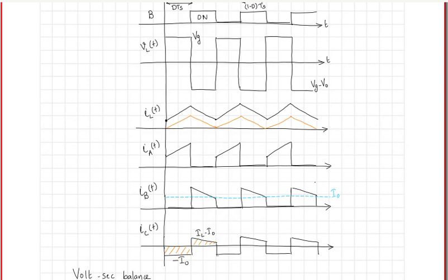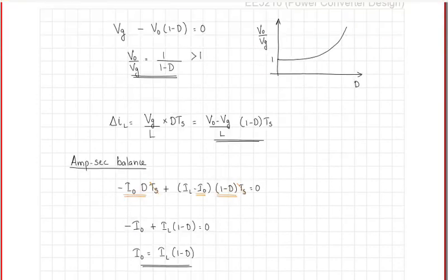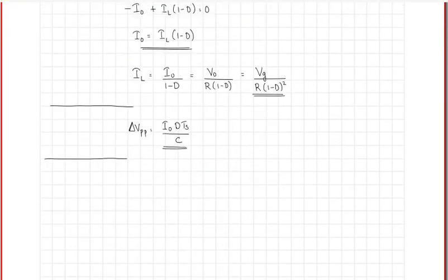So what we now would like to understand is at what point the operation of this converter is going to move from a continuous conduction mode to the discontinuous conduction mode. So this operation is what we typically call the boundary between CCM and DCM. We have seen this boundary in the case of the buck converter also. Now we will look at what is the condition for this boundary operation in the case of the boost converter.